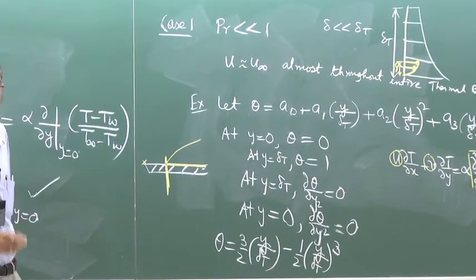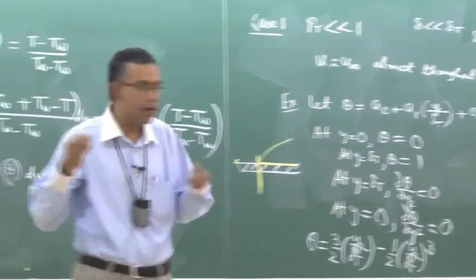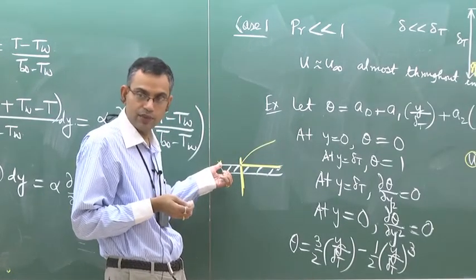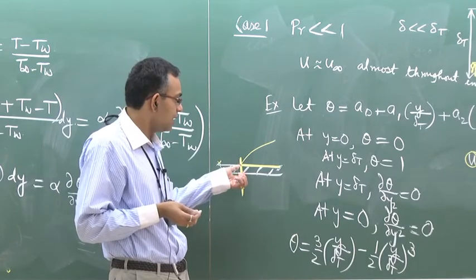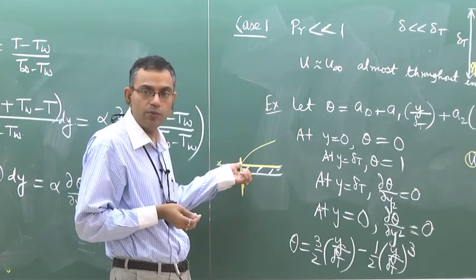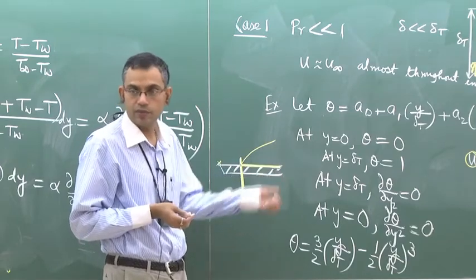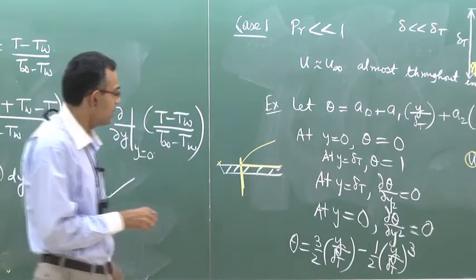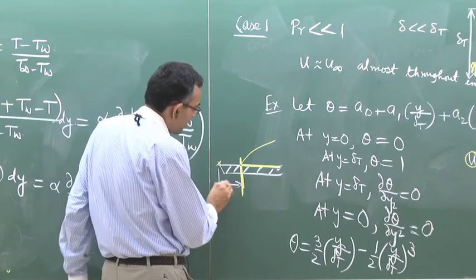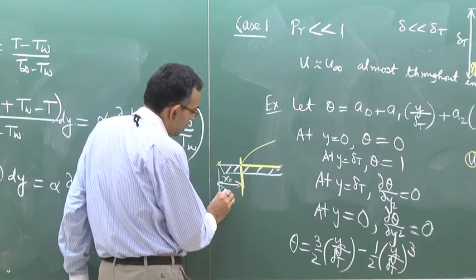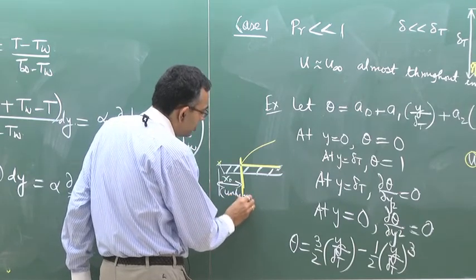Okay. So the hydrodynamic boundary layer, the frictional effect will be felt starting from here itself, but the thermal boundary layer, the heating or cooling effect of the wall will be felt only from that location from where you start heating or cooling. So you may have a length x0 which you may say as unheated or uncooled starting length.